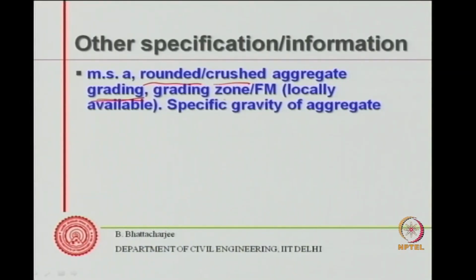Similarly, for sand, the grading zones may be important. Again, that's telling us what is the size fraction, the proportion belonging to each size fraction. Fineness modulus, also we have discussed sometime earlier, is a kind of measure of an average size. So packing characteristics are governed by shape of the aggregate, maximum size of aggregate, and proportion in each size. These informations are important from the point of view of availability of aggregate, because one would like to use